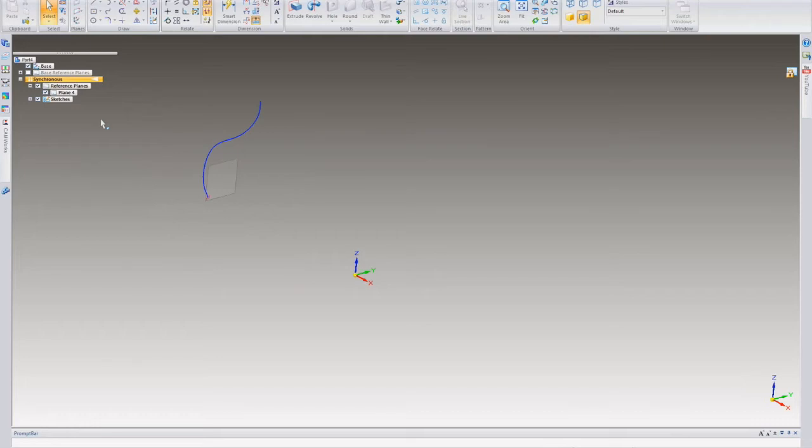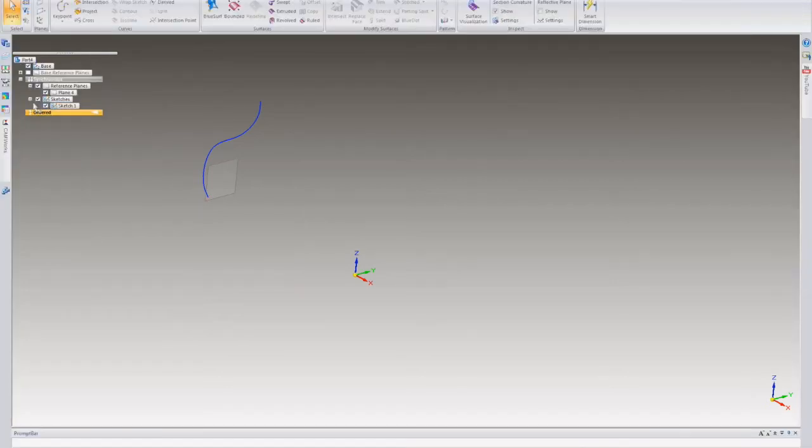All right, so to get what I need, I'm actually going to take this into an ordered environment. I'm going to go ahead and create a couple different shapes and sweep through space. All right, so what I'm going to do is quickly transition to ordered. The reason I do this is the sketches are controlled differently in the synchronous style than they are in the ordered environment. So I'm going to go ahead and mirror that sketch over, so I'm copying and mirroring a sketch from the synchronous to the ordered environment.